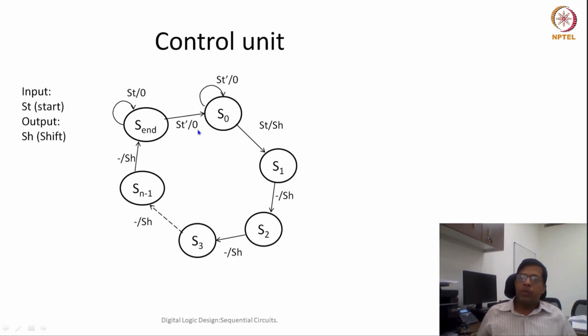So one more important thing to notice here: the state machine is written in a slightly different format. So far, whenever we were writing the state machine, we were writing 0 or 1. Now instead of 0 or 1, we are writing the variable name directly. What is that and why is it so? This is a visually different way of representing the state machine, where we need not bother whether it is 0 or 1.